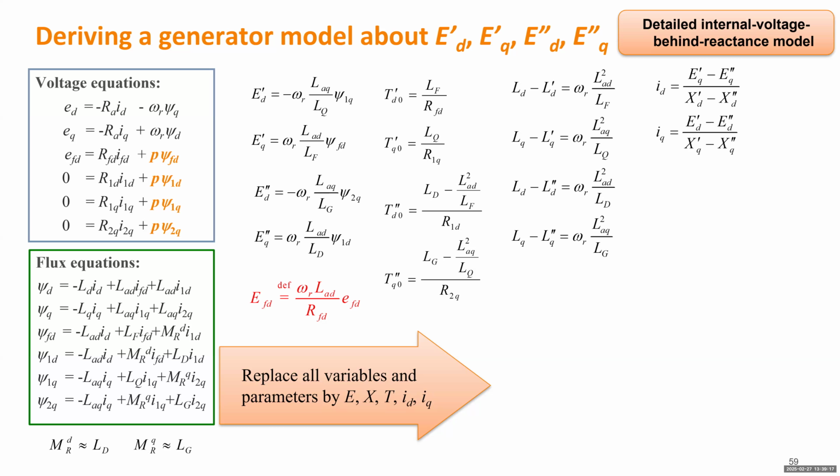get those two equations. Another thing you can utilize is, because so far we talk too much about the inductance, right? You may be more sensitive to see anything like one L minus another L. But once you put everything in per unit, you can replace L by X because L and X are basically the same. So you can be sensitive enough.